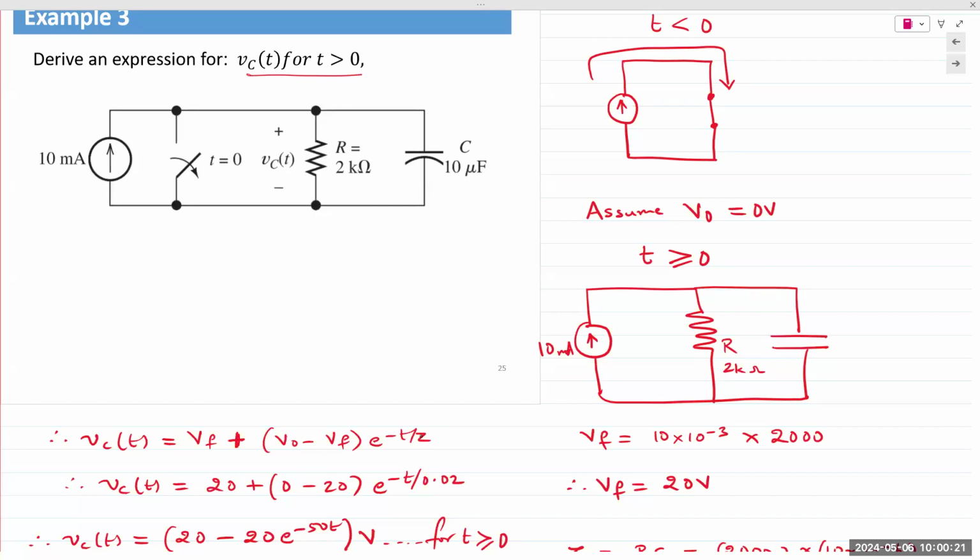If you have a short circuit in any electric circuit, anything that's in parallel with the short circuit is effectively removed, because all the current would just go through that short circuit. Everything else is kind of redundant.